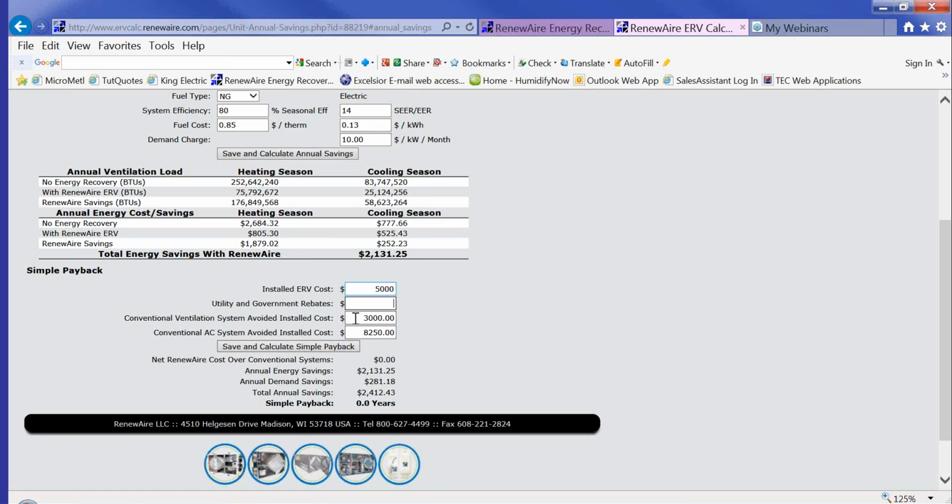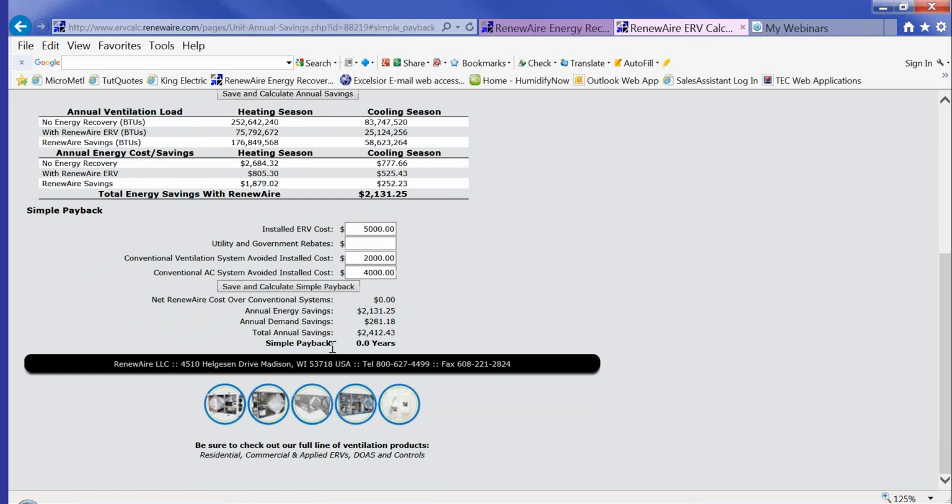And these are the dollars that you would save by not having to get a conventional system for the makeup air, for 100% makeup air. So let's put in 2,000 CFM. And these are the cooling, the AC costs that you'd save for the 5 tons or so. So let's say it's maybe $4,000. All right, and of course this one, if we do the savings right away, the $2,130, $3,100 right there in the first year, you can see the savings are immediate.